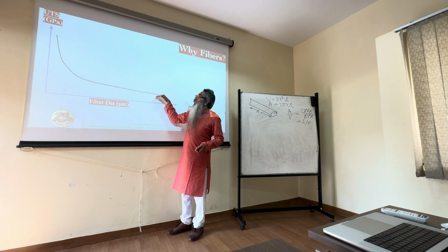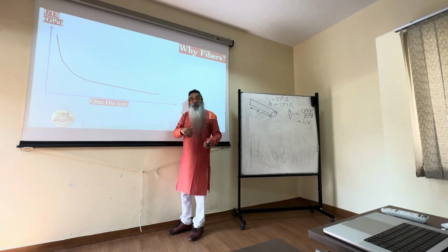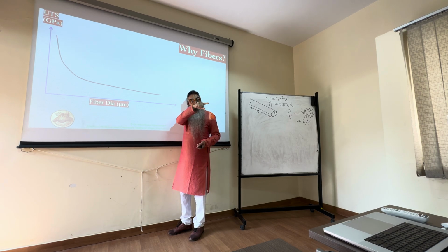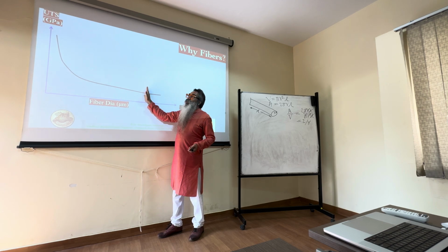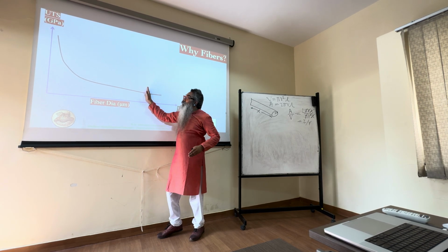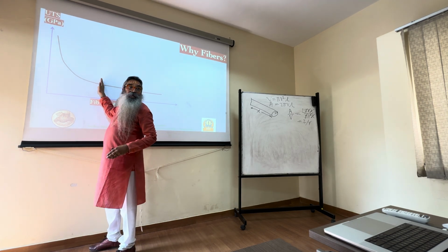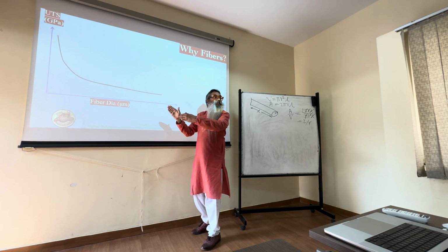In other words, there's no change in the UTS with the fiber diameter. So many of you, when you said that the answer is constant, parallel to the x-axis, earlier, you were right if you are talking about only this region of the spectrum, right? And those of you who are talking about this drop, yes, you are right too, right? So it's just a question of what range of diameters I take.